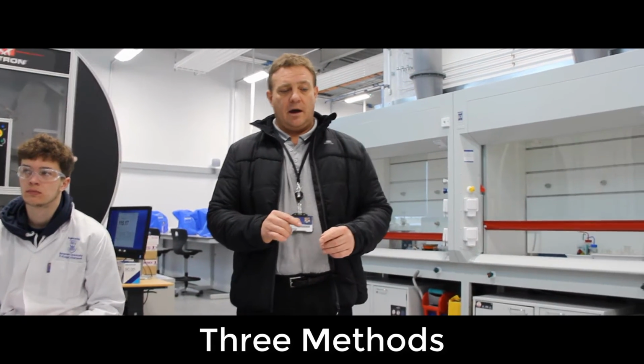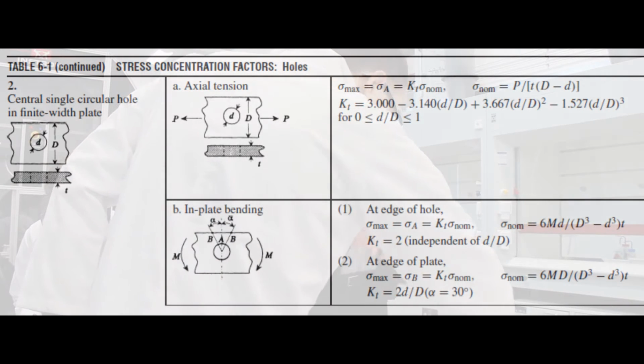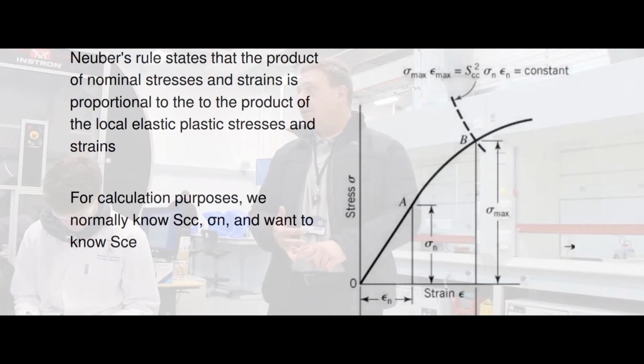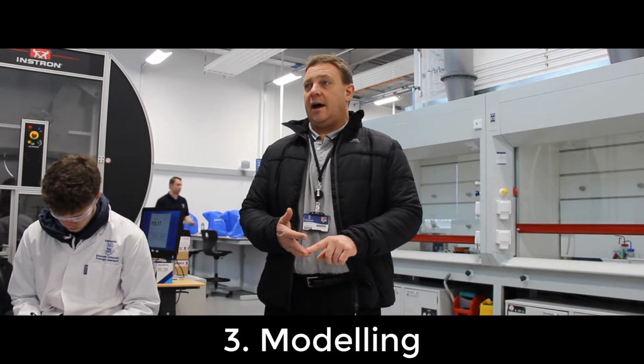The key thing about the entire assignment is that you've got 3 different routes by which you can evaluate the effect of the stress concentration on the strength of the component. You've got the empirical method, where you've got a series of equations that give you stress concentration factors. You've got your experiment, which will give you force displacement, and then you can also work out stress concentration factors from Neuber's rule. And then you've got the modelling, which will, at its most simple, give you out a graph or data of force displacement, much the same way as you will come out of the machine. In all of these cases, you can work out stress concentration factors from the 3 different routes. So the ultimate aim here is to be able to say, this is the empirical, this is what our experiment told us, and this is how the modelling told us stress concentration factors.